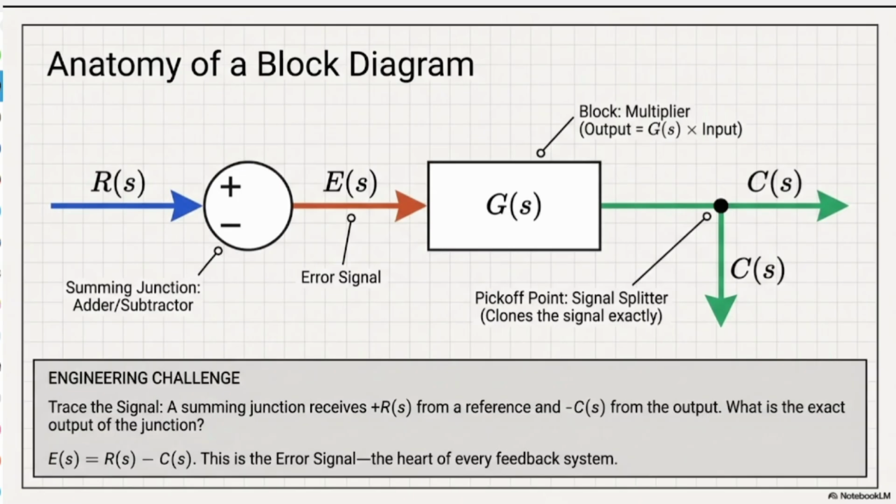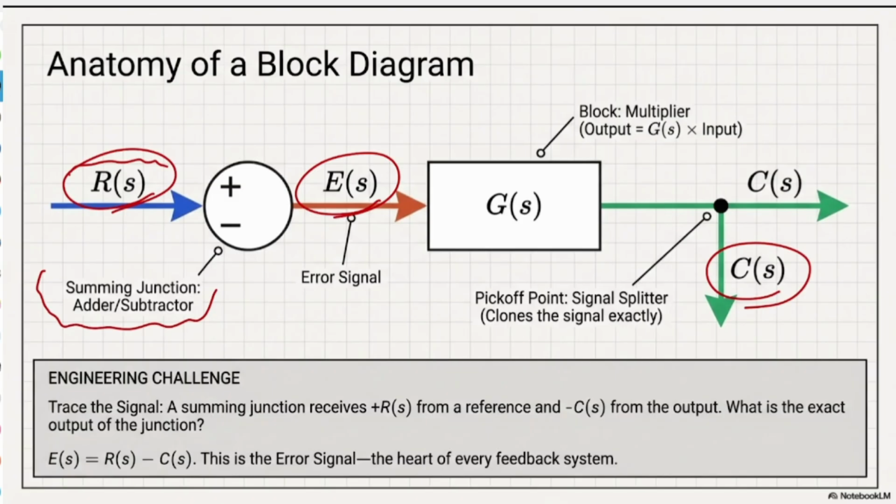So at the very beginning, we have to start with a couple of definitions. You already know about that, but it is good to review. Imagine that you have a feedback control loop system, which, as you know, we call a closed loop control system. For each control system we have different parts. The very first part is the input. Input most of the time is a set point, or a number that we would like our system to reach. Then we have the summing junction, which is considered an adder or subtractor based on your feedback. It is there to find the difference between your feedback and your set point, and then it makes what we call an error signal.